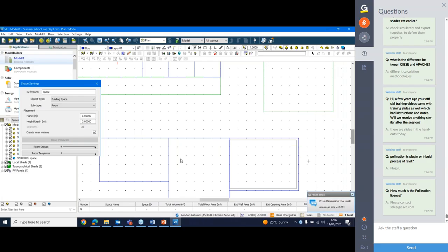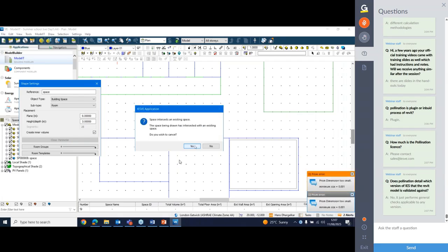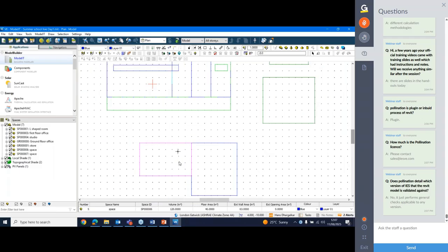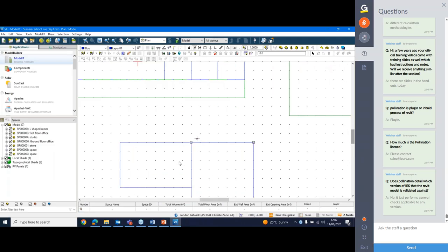So when we use our thermal software, we draw it like this. The only time you might want to use the inner volume is if you're using our lighting software and you had a really thick wall and you want to take into account the inner window reveals, which might have an impact on the light levels of the room. So you could set your window sill or window reveal header to a particular reflectance or color. Okay, but typically we don't use inner volumes for thermal. So when you're drawing your rooms, you assume that you're drawing around the inside of the external wall and halfway down the internal partition. Brilliant, thanks, Hans.